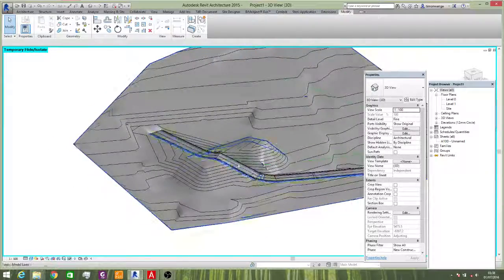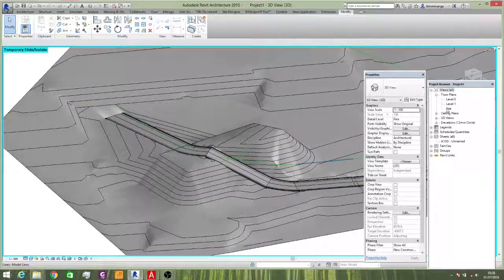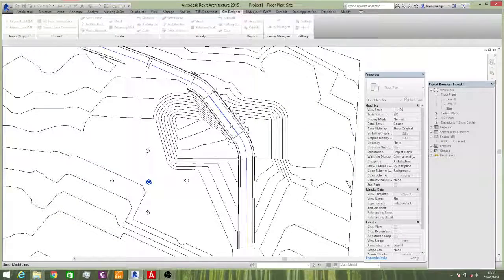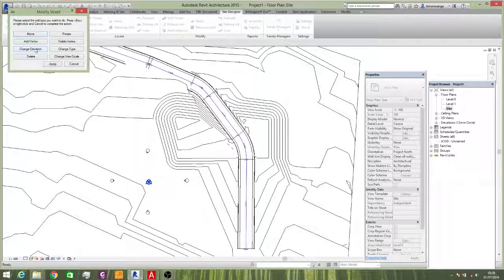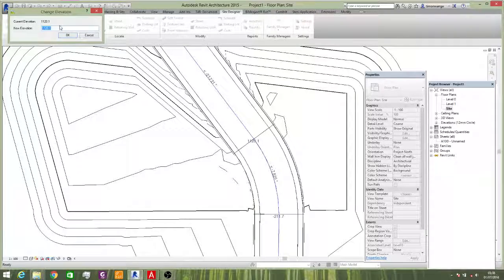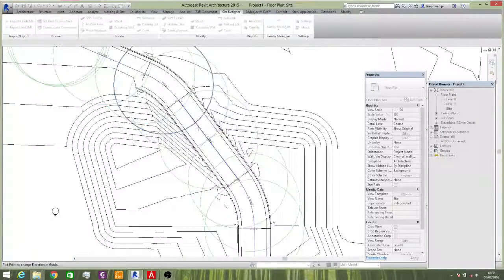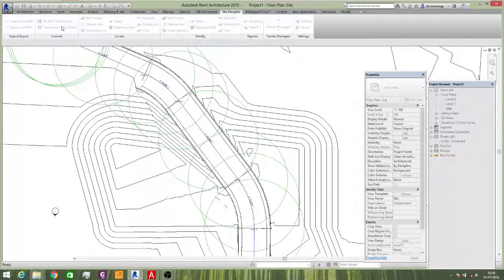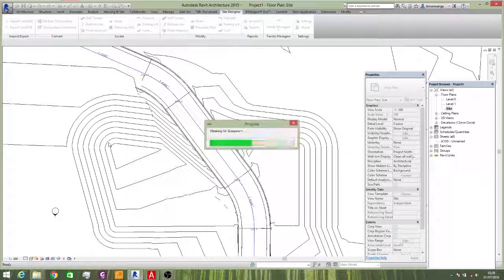Well, if you're not so much satisfied with what you've created, then you can go back to the modify as usual. Modify street, then pick a line from which it was sketched. Say I want to change the elevation, it's too high, so you pick that, change the elevation maybe to 500, say okay, change that again to -8,000, say okay, cancel, apply, or even move it if you want, or even delete it. It creates the mass grades for you, and you have your road.